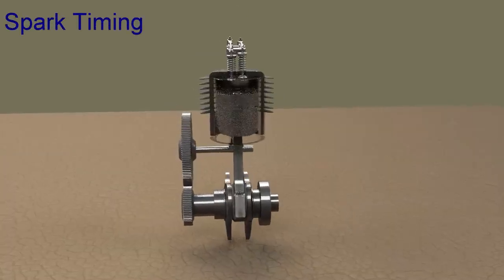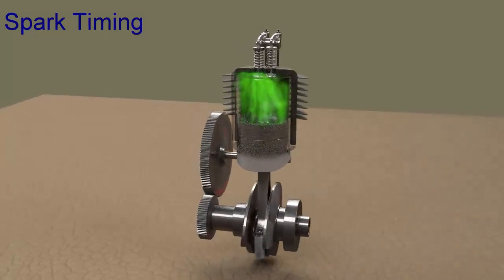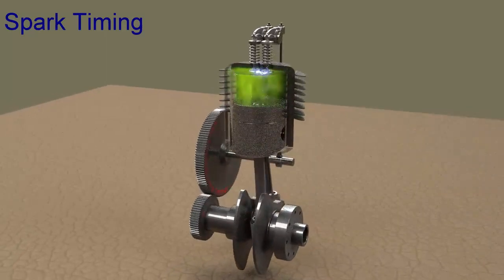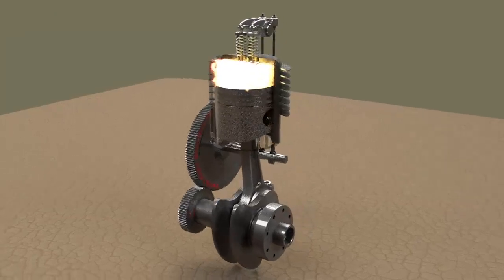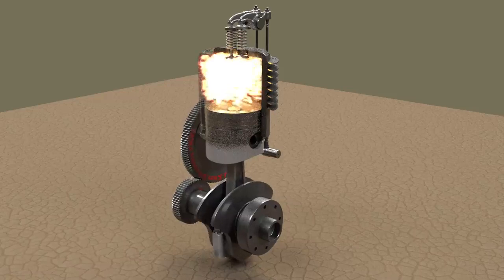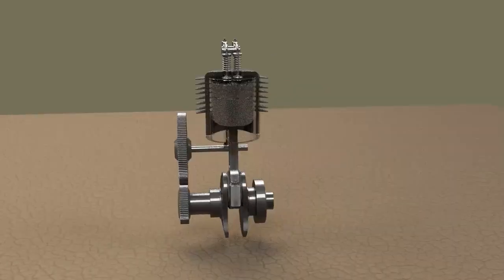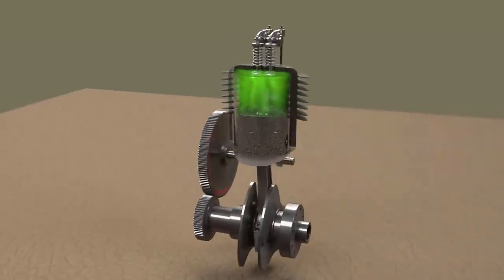The electric spark has to happen at exactly the right time or the engine will not run properly. For example, if the spark occurs much before the piston reaches top dead center, the fuel will pre-ignite and the increased pressure may lead the piston to move in the wrong direction, which will eventually stop the engine. Newer engines typically use a computerized ignition system for controlling the timing of the spark.